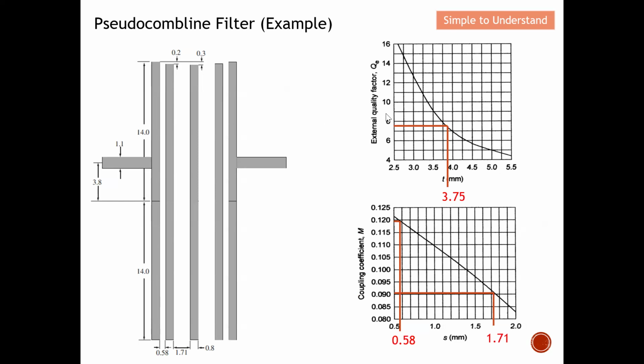So let's come to the design. We have done this early on with 3.75. It's the spacing between the center, so you actually have the lambda over 2. This will be the center. Whatever the difference, you adjust from here, which means this part will have some difference. This part here will have a quarter wavelength. This part will be a virtual short circuit over here. We calculated earlier on, which is about 3.75.